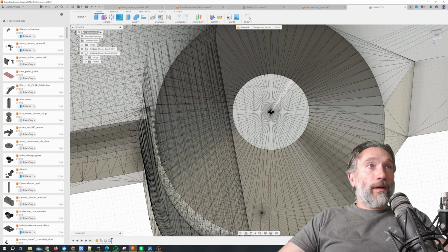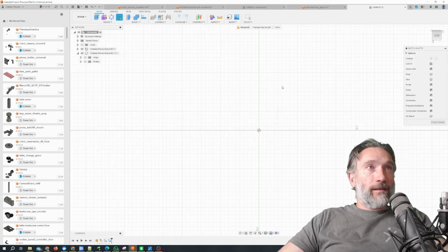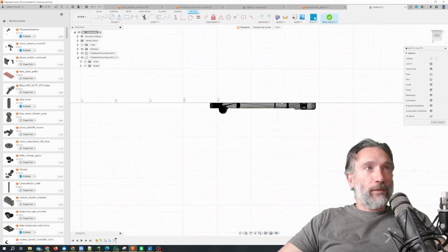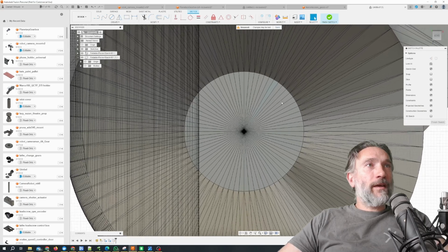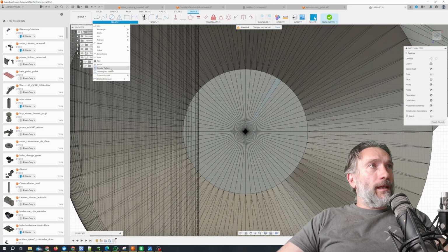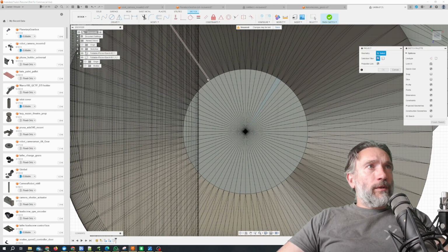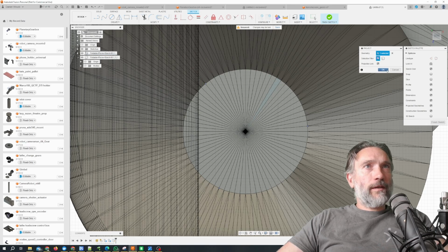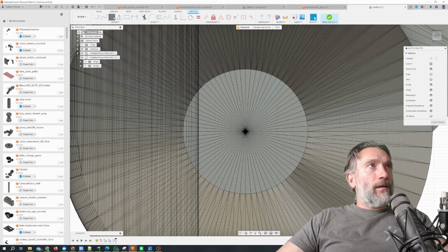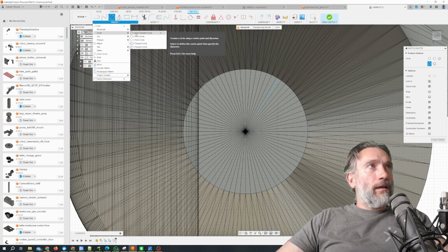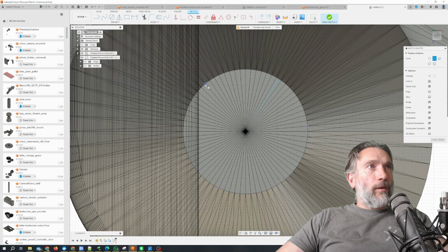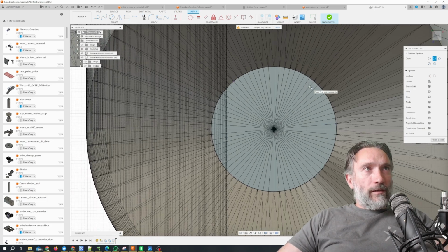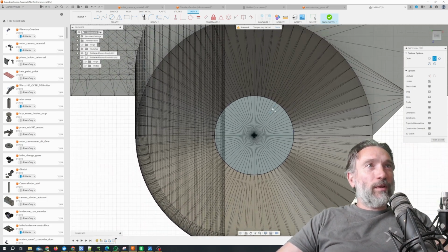and that is we're going to create a new sketch surface. We'll pick any one of these faces to be our sketch surface, and it will jump us to the wrong place because it's helpful like that. And what we're going to do is say project. Project is a great way to bring stuff in. We're just going to pick any three dots that are roughly thirds around on that surface, and then we're going to create a 3-point circle. So select the points that we just projected, and now we have a perfect circle on that plane.